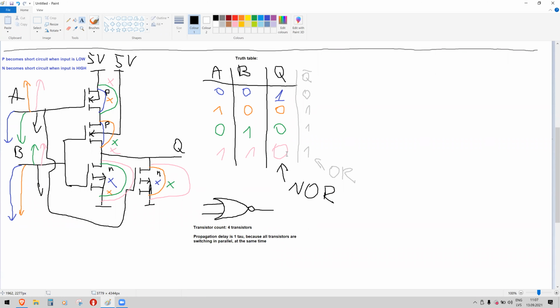output is 0. For example, for OR, you could have A or B or C. You could have multiple inputs, and the result would be whenever one of the inputs is 1, the output is 1, and only if all inputs are 0, the output is 0. So the same would apply also for NOR and also for transistor connections. So you can write in chat, can we build a NOR with more than 2 inputs, and how could we do it?